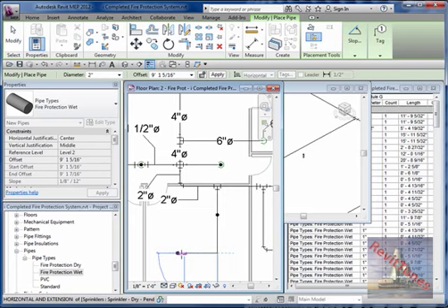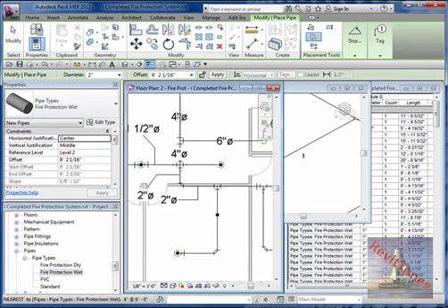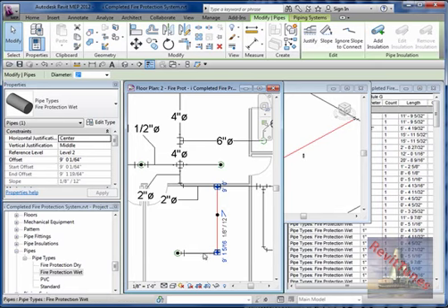Click, and okay, so we got the message again, and remember it's because this is a dry system, this one right here, and this is a wet system, and until I put a certain valve here it will not give me that message. But for now I'm going to do just the pipes. I'm not going to put the valve here. Alright, so now we know this is okay.